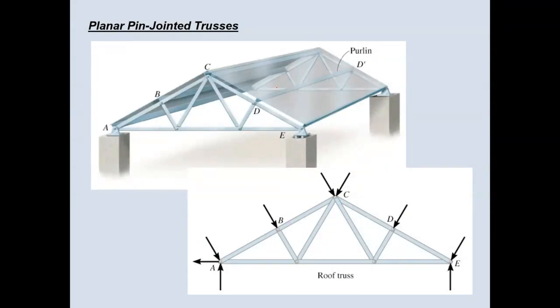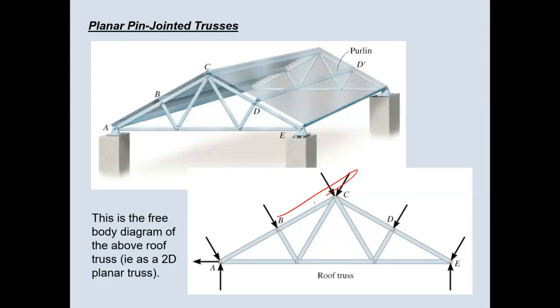When I release the roof from the structure, the external forces at A, B, C, D can only act at the hinges. They cannot act between two hinges. And therefore, each individual member can only elongate or shorten. They can never bend. In other words, BC eventually becomes longer or shorter. You never get BC to bend like that. If that happens, this is not a truss.